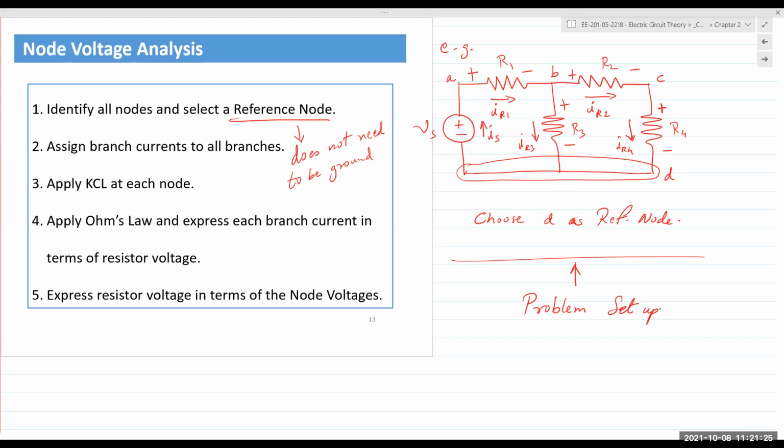All right. So as you can see at B, you can see minus, plus, and plus, right? Those are for three different voltages. It's not as if B is like minus, plus, and plus. It gets confusing for some students. That's just because it's showing that B is lower than A, but it's higher than C and D. That's why you have a minus, plus, and plus, right? So voltage polarity is just noting the difference between the two nodes that the resistor is connected to. That's all it means.